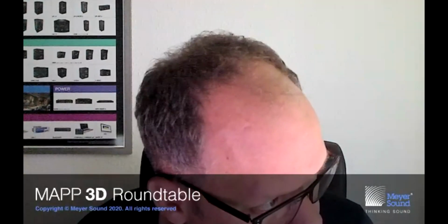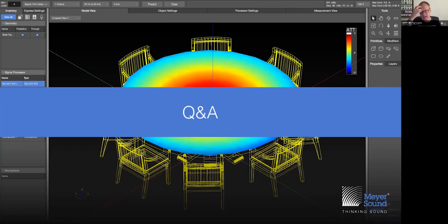Alex, I would respond that there are no tools to edit DXFs or SketchUps once they are imported. So the best thing you could do is to edit that in the AutoCAD or SketchUp software and then re-import that drawing, because, like I said, there's no way to edit an imported drawing. So yeah, that's mainly something you need to do before bringing it into MAPP. So you can always re-import and just discard the old one.